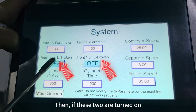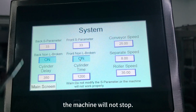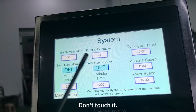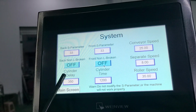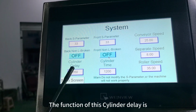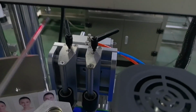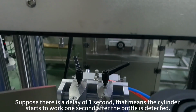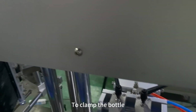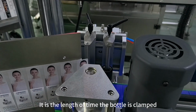If these two are turned on and the label is broken, the machine will not stop. It will continue to run. Turn them off. Don't touch it. Cylinder delay and cylinder time. The function of cylinder delay is how long it takes for the cylinder to start working after the sensor detects the bottle. Suppose there is a delay of 1 second. That means the cylinder starts to work 1 second after the bottle is detected to clamp the bottle. There is a cylinder time. It is the length of time the bottle is clamped.